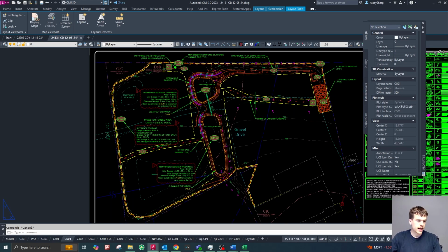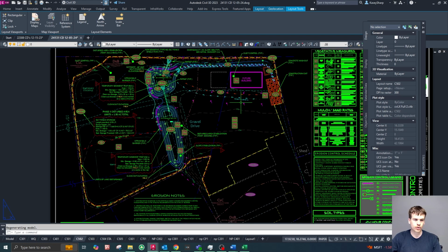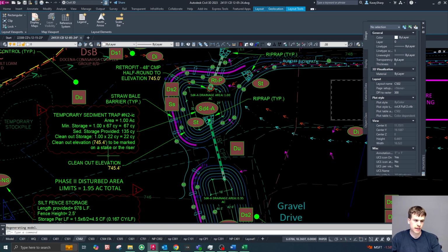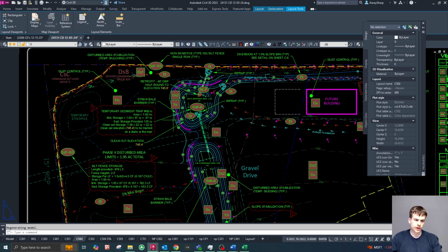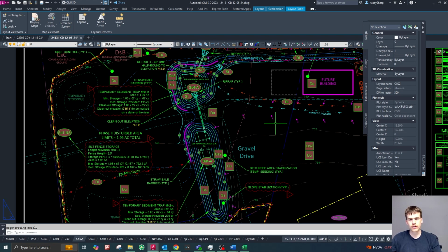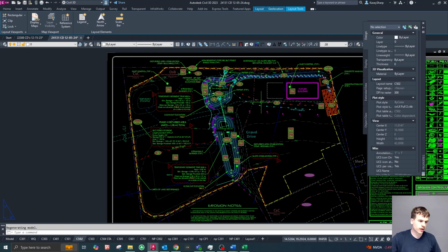Okay, this is going to be the installation of a concrete washout, construction exit, and any other BMPs that are located on site. And then in our phase 2 erosion control, they're going to start grading out our stormwater facilities. They're going to grade out the ponds and start pad grading for buildings. If you notice here on this plan, our temporary sediment traps also double as our detention pond. So we designed our detention pond, and then we designed our sediment trap to be in the same location, and either partially the full depth of the pond, or in phase 2 they'll dig out the full depth of the pond, such that contractors don't have to dig out sediment traps and then refill them later and then dig out the ponds. So they're not double working. That's one of the common things that you'll see.